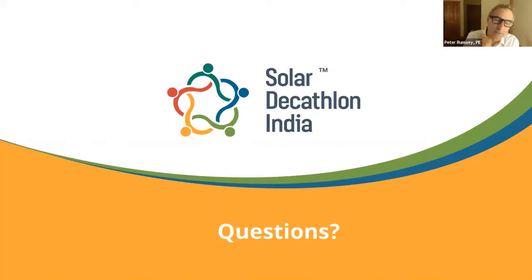It's a very important load. It's one that the engineer has to take responsibility for. That's why I was saying ventilation is a load. Ventilation is the air that we bring in, so that's where we cover the humidity question. When it's a dry day, it uses less energy to cool the air because we're not dehumidifying it.